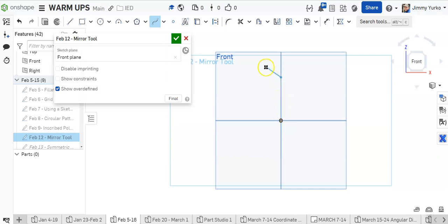And I'm going to have my work planes turned on, and we're going to begin by clicking and releasing the mouse directly above the origin. And then I'm going to click 2 points in this upper left quadrant. I'm going to put a third point, or final fourth point, by double-clicking directly below the origin.